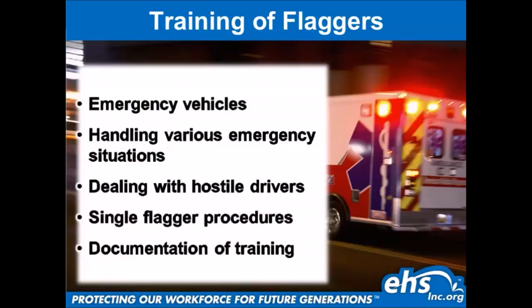What to do when dealing with emergency vehicles. And of course, there's not just one thing that may happen when you're dealing with emergency vehicles. You can have advanced warning, you hear the sirens at a distance, and you can have, let's say, a police officer stuck in traffic and then having to respond to an emergency when they're close to your site. So there are different ways of handling various emergency situations, and dealing with hostile drivers, which, if you talk to your work crews, these guys are dealing with hostile drivers, it seems like every day out on the roadways. Single flagger procedures, and of course, just like anything else, guys, documentation is key.